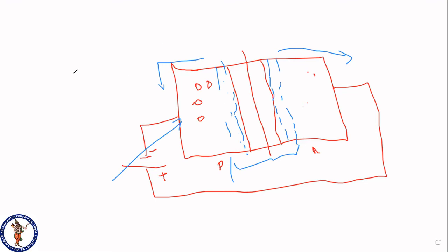The current flowing is very less and approximately 0, but we cannot take this approximation. There is still some current that will flow, so in reverse bias we take it in microamperes. In forward bias we take it in milliamperes. The diode IV characteristics is different. Generally we take both in the same units, but in this case, for forward bias we have to take milliamperes, and for reverse bias we have to take microamperes.